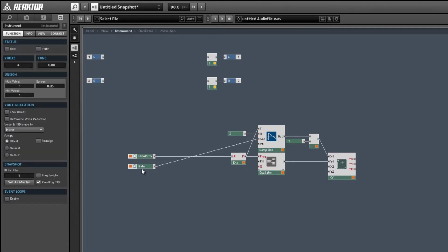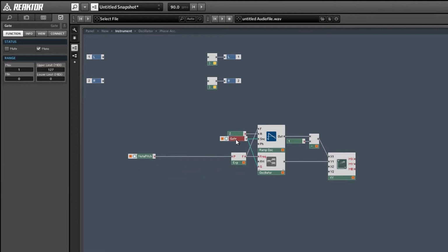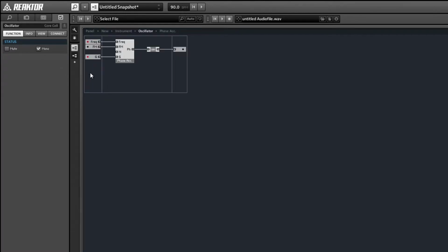So now that we've verified that our frequency modulation system is working properly, I'd like to add phase modulation to our oscillator. And while phase modulation is less well known than frequency modulation, as a name anyway, a lot of the things that you think of as being frequency modulation, such as the Yamaha DX7, are actually implemented using a phase modulation structure. And so what phase modulation is, we're going to take the output of the phase accumulator that we've created and modulate it with another audio signal.